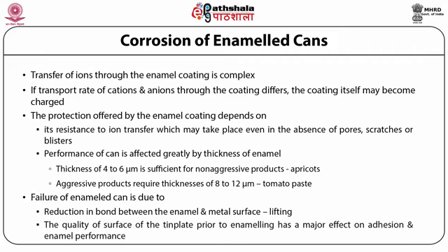The quality of the surface of the tin plate prior to enameling has a major effect on the adhesion and enamel performance. The presence of salt residues can cause failure due to their ability to attract water and therefore establish a conducting film beneath the coating and to provide ions for carrying the corrosion current.